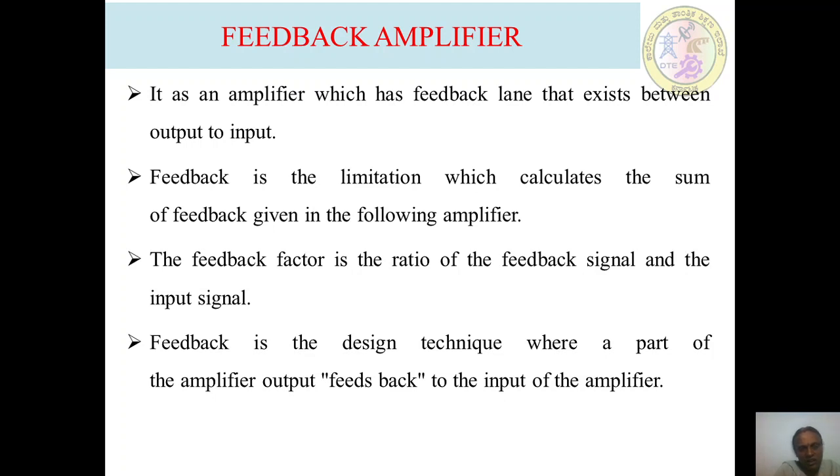Therefore, every high gain amplifier tends to give noise along with the signal in its output. This noise is undesirable. Hence, the noise level in the amplifier circuit can be considerably reduced by using negative feedback, done by injecting a fraction of the output in phase opposite to the input signal.